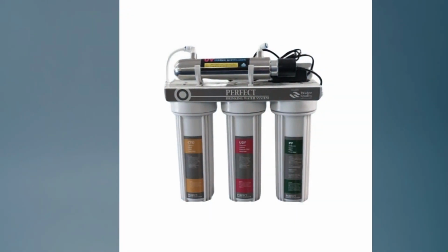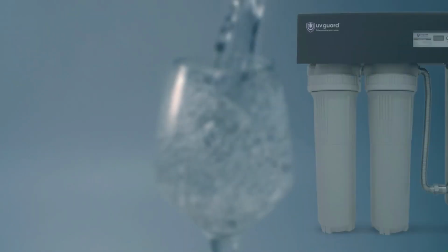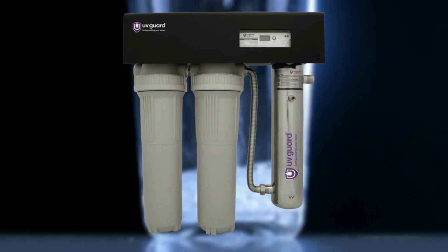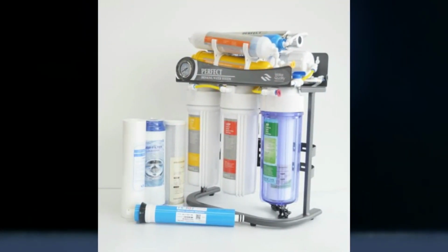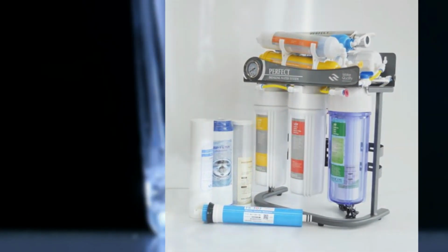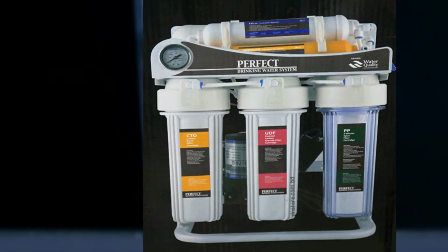4. Control unit. Function. The control unit manages the power supply to the UV lamp and may include features such as a timer, a UV intensity monitor, or a system diagnostics display. Advanced features. Some units come equipped with alarms or indicators to signal lamp failure or a decrease in UV intensity, critical for maintaining system effectiveness.